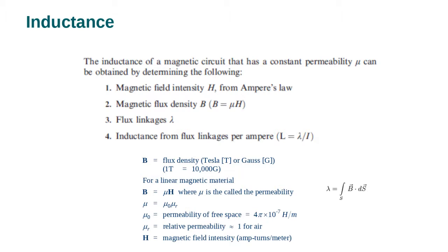Then we add an inductance. What does the inductance cause? It causes voltage drop. Okay, not real power loss. It causes voltage drop. So I square X, that is voltage drop. Then we need to include the inductance. The 4th parameter is the capacitance that we're going to talk about next lecture.